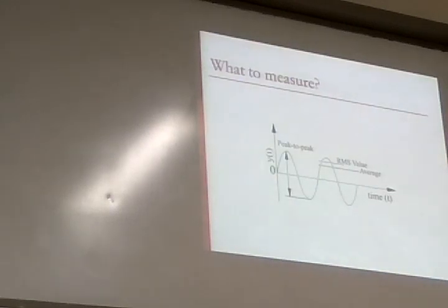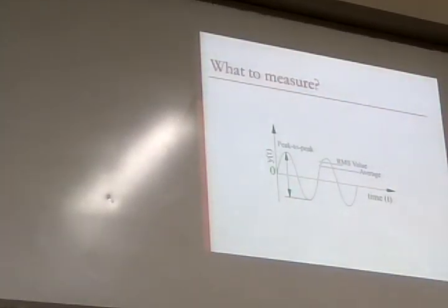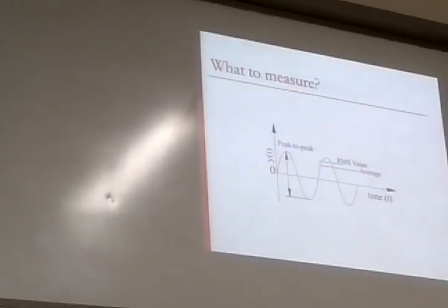The mean, standard deviation, kurtosis, skewness, minimum, maximum, standard error. There are 12, 13 parameters. We call them statistical parameters that we use. Also, we might plot a histogram of vibration and then use histograms as a feature. So, you have plenty of parameters that can be used to represent a vibration signal. Very primitive quantities are peak to peak value, RMS value, average.